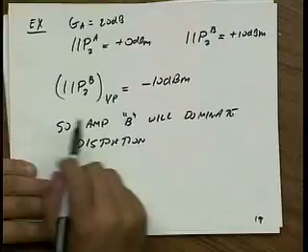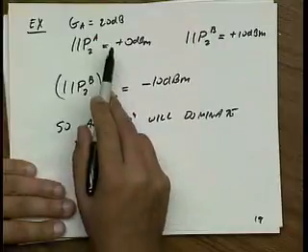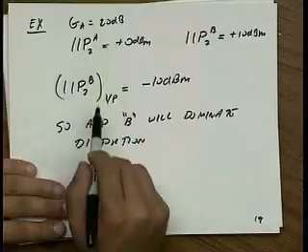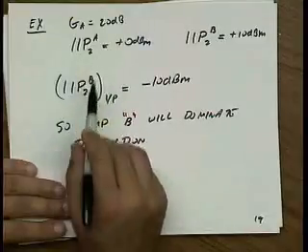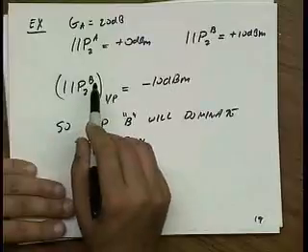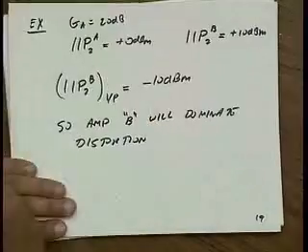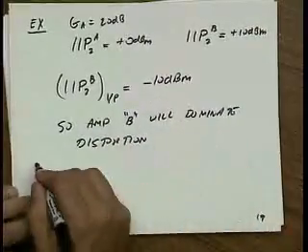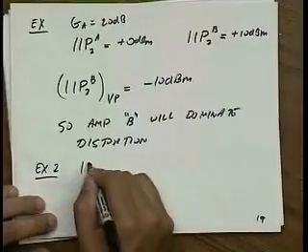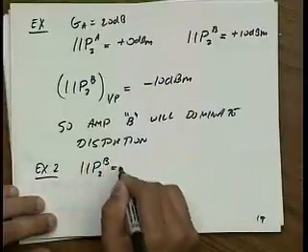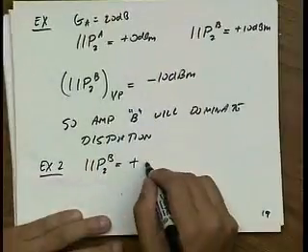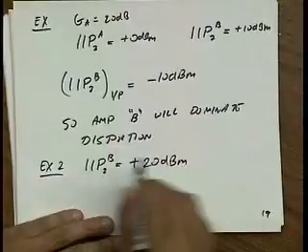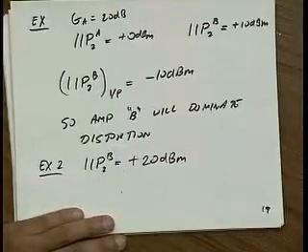If on the other hand this input IP2 point is close to this point, then I use the law that they're in parallel. So the overall IP2 is worse than the IP2 of either one. So if they're both equal, let's take another example. Let's say I use the same first amplifier, but now I go out and buy a more expensive amplifier that has a 20 dBm input IP2.